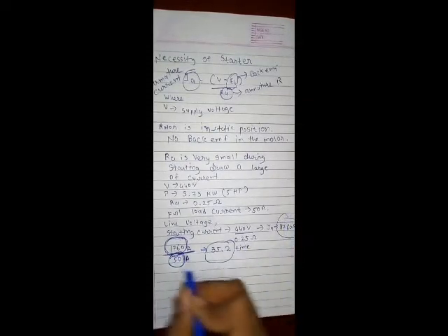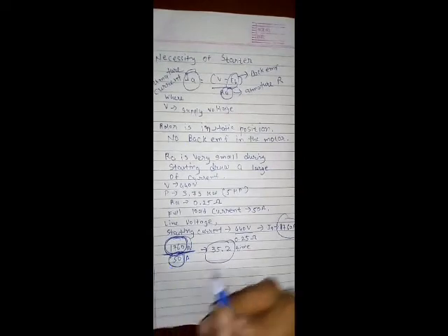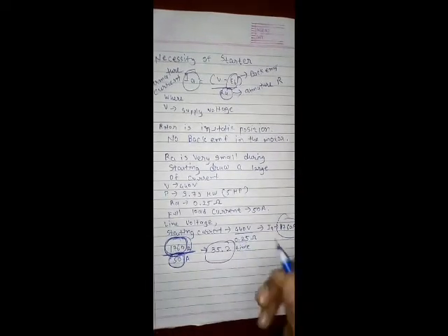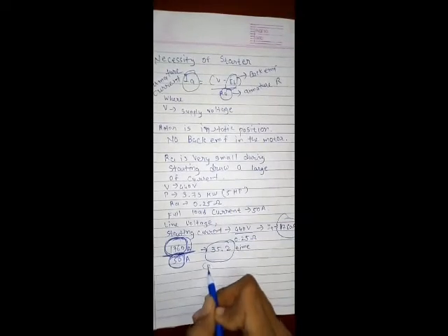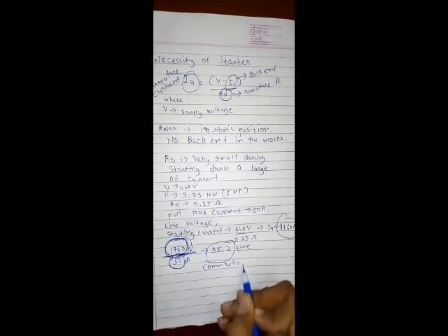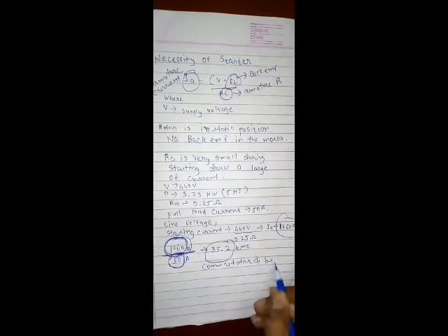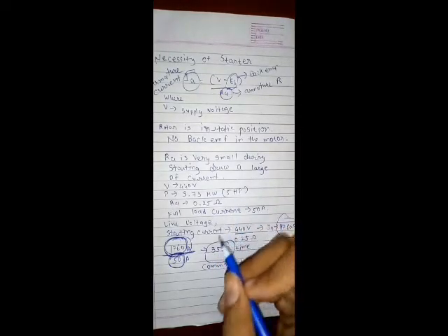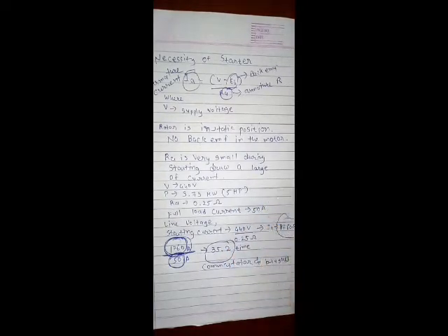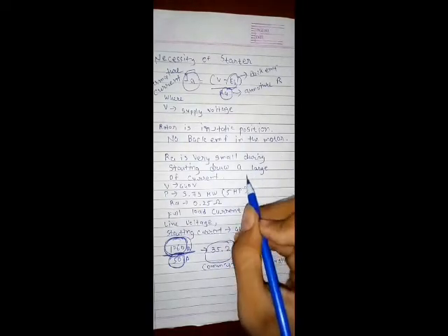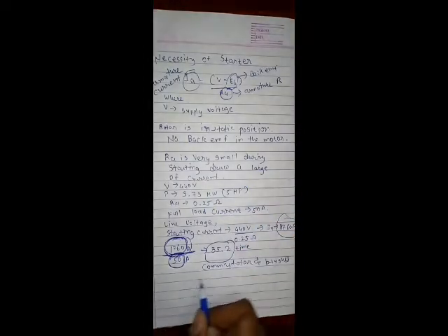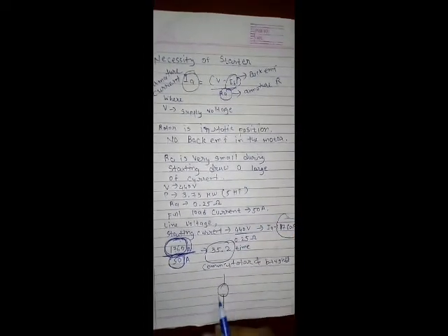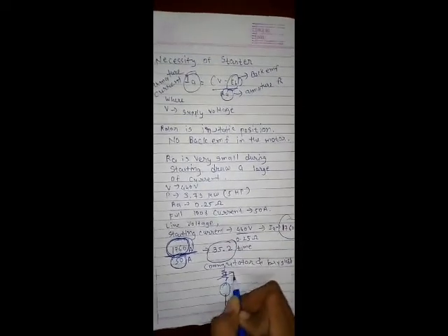This excessive current will blow out the fuse, and prior to that it will damage the commutator and brushes. To avoid this, a resistance is introduced in series with the armature only during the starting period, which limits the starting current to a safe value. This is the armature of the motor, and a variable resistance is connected in series with the armature.